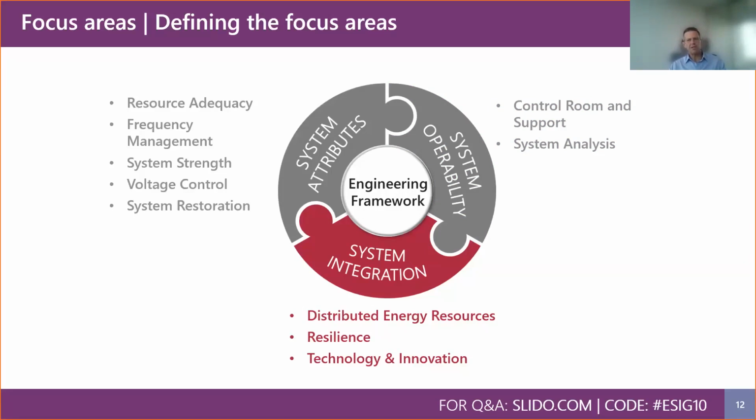And key matters that AEMO is looking to pursue and consider in this area include observability, because DER is currently not visible to AEMO, the predictability, because of unknown or unexpected behaviours of distributed solar PV to frequency and voltage disturbances, for example, and the last lines of defence, that is, under frequency load shedding, because operational demand is offset by DER and therefore removes that capability.